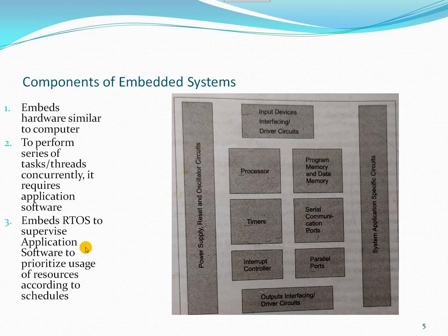Whenever we are dealing with operating systems in embedded systems, they should not be general purpose operating systems. They should be real-time operating systems, because general purpose operating systems have all the components of a particular computer software, which may not be required for a particular embedded system. So in order to cater to the particular need of an embedded system, we will tailor-make that operating system into a real-time operating system.